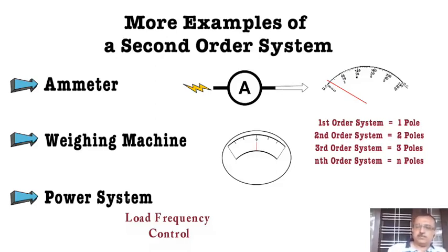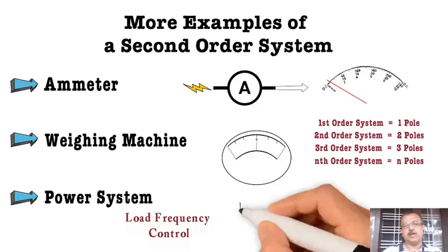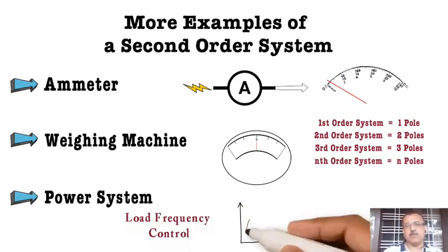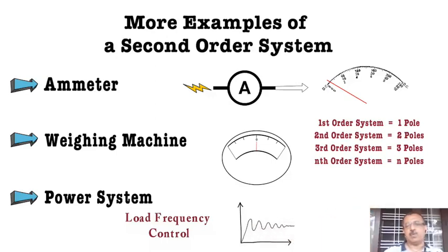I'll open up the valve, then there's a sudden inrush of water. Then what will happen? The frequency will go up. You'll see that the frequency will have an oscillation of this kind. If I plot delta f, I'm not plotting the absolute frequency, I'm plotting the deviation in frequency. The frequency was 50 hertz, 49 hertz now. Then when I give a slight change in the input, the frequency will oscillate and settle down. This phenomenon could be there in many examples.